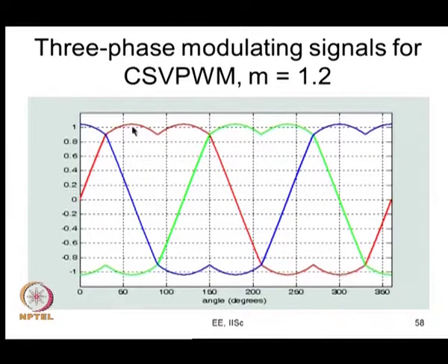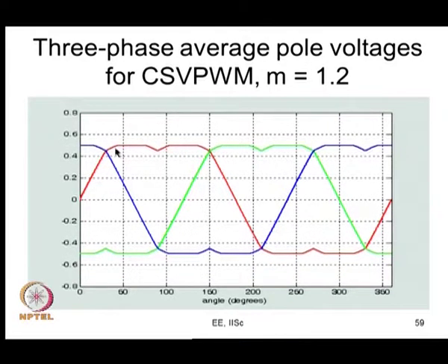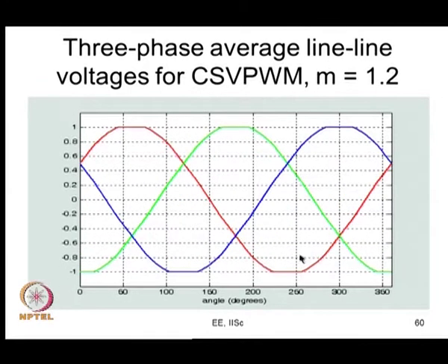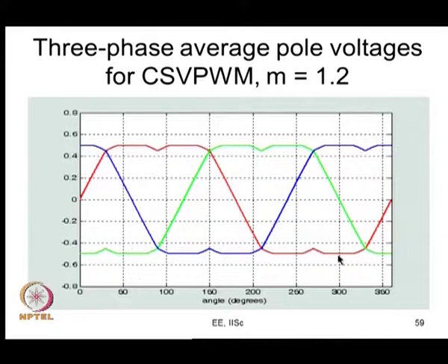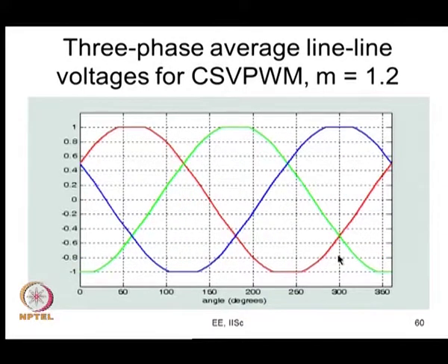These are regions where you are going to get clamping for R phase, and similarly for the other phases. This is pulse dropping. There are no pulses here, while there are pulses here: the R phase switches here, it does not switch here, the pulses would be missing. So, it is called pulse dropping. You have pulse dropping here and also here and here for all the phases.